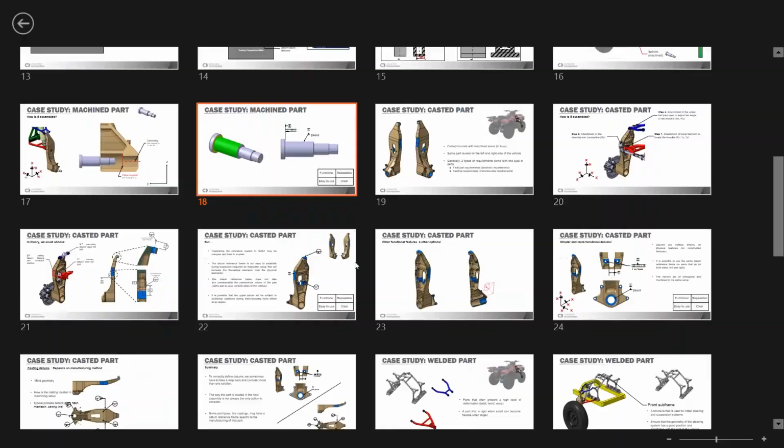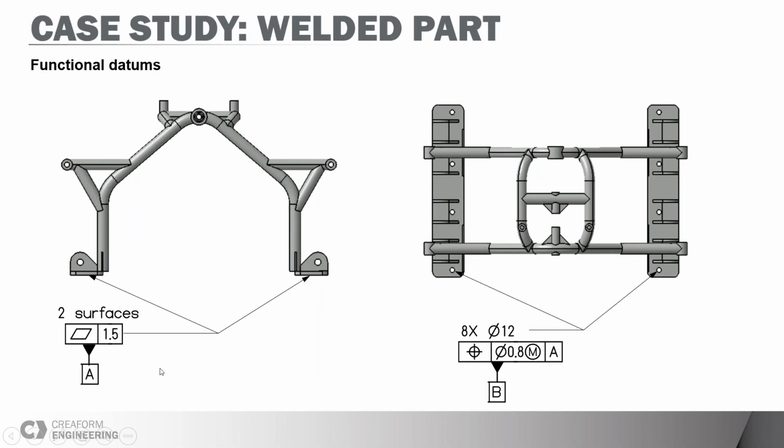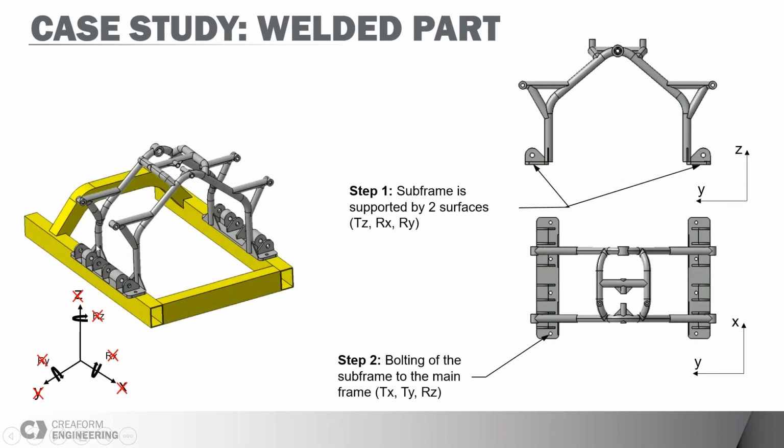Another case where we had the requirement of tolerance on our datum was this one, for example. This is a bolted interface, so we have a flatness on that interface. The value that we will put there will be the gap value that we are able to accept between the part and the next assembly, so between the gray and the yellow part in that example. As you can imagine, 1.5 millimeter of flatness plus the flatness of the yellow part as well. This will be the maximum gap that we will allow between the two parts.